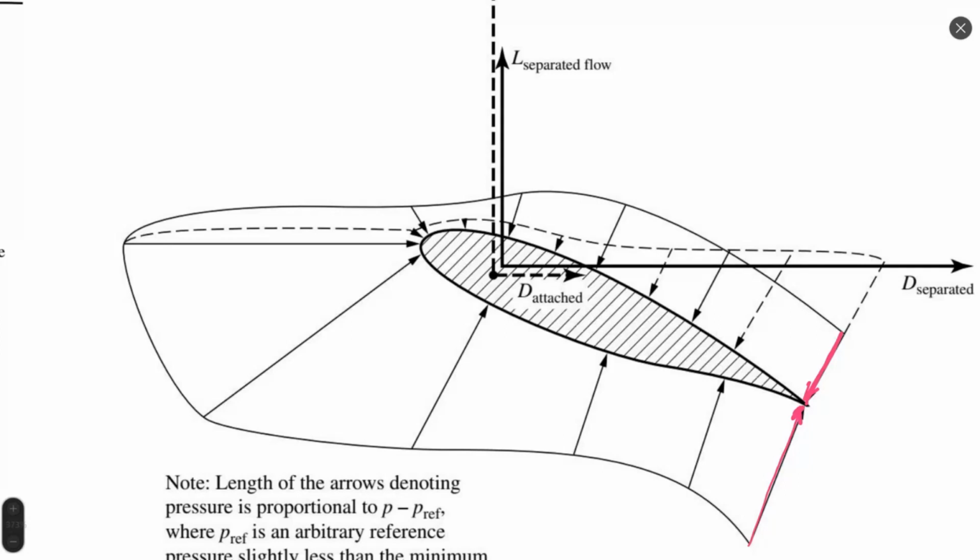For separated flow, you see equilibrium between upper and lower side pressure exactly at the trailing edge, and then this separated pressure, of course, naturally decreases because flow goes in opposite direction. And there is a region of flow separation. We cannot say from this picture where exactly flow separation starts, at which point, but we see that pressure acts against the flow. So it provokes flow in backward direction.